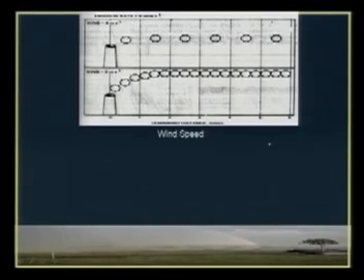This is a little graph or picture that shows the effect of wind speed on the concentration. Imagine there is a chimney, identical here, here and here, and here the wind speed is very high. What is the range of wind speed we are talking about here? 6 meters per second. And suppose the wind speed was reduced to only 2 meters per second.